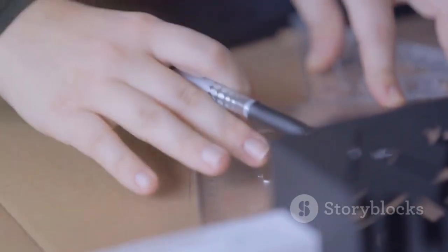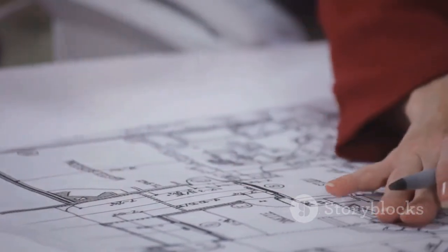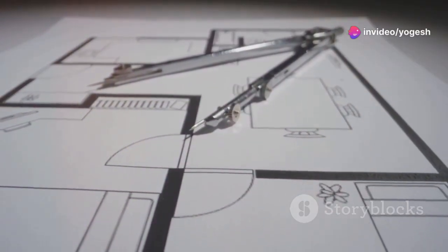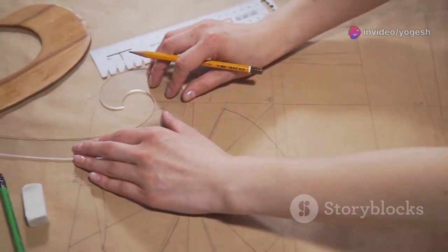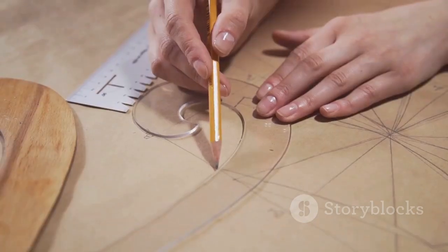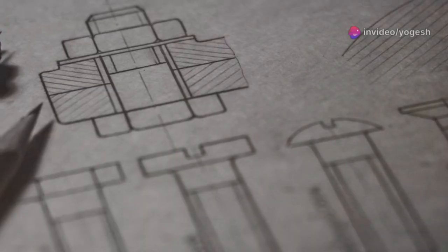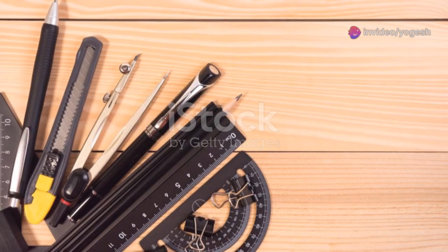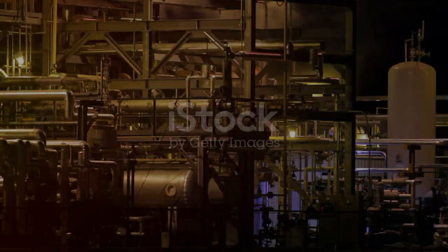Next, transfer depth from the top view, measure the distance from the reference plane to each feature, and mark it along the corresponding projection line in the auxiliary view. Connect the dots, and you reveal the true, undistorted shape of the slanted surface. Holes appear as perfect circles, edges as true lines. This method guarantees accuracy and clarity. It's a logical process, no guesswork. With practice, it becomes second nature. That's how you turn complex geometry into clear, buildable drawings. Auxiliary views make it possible.